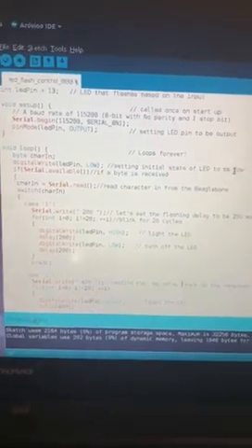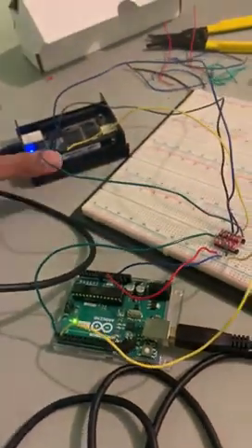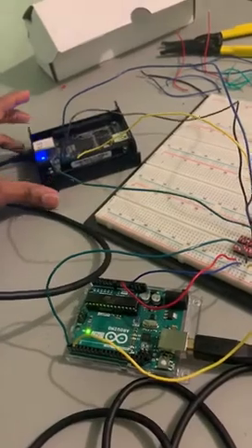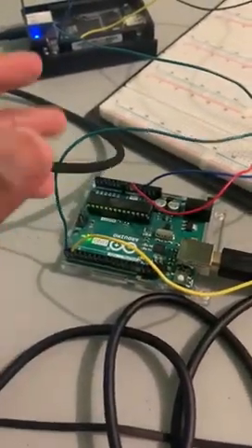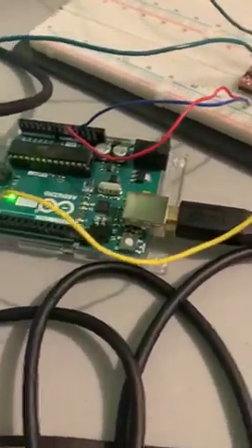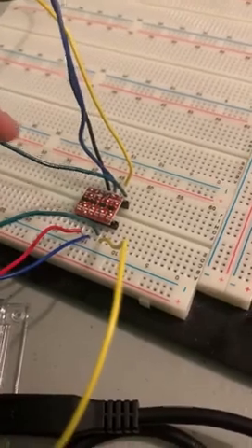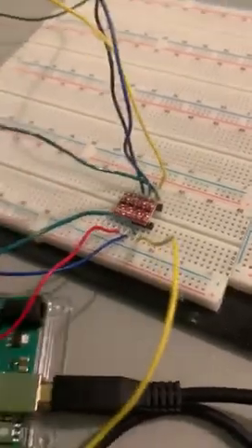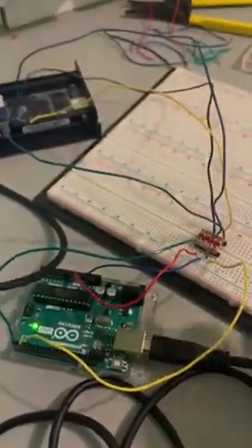Everyone, here we are trying to interface the Arduino Uno board with the Beaglebone Black through the UART interface. So this is the basic circuitry used. We have used the UART transceiver pins of the board and connected it to a logic level converter so that we'll get the low logic levels for the Beaglebone Black. So this is a basic circuit setup.